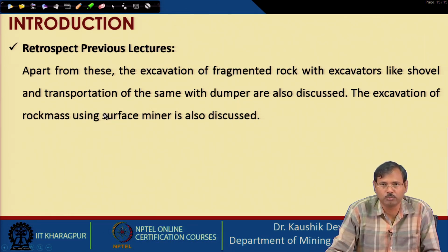That is the problem with the stripping shovel, and it has to work from the bottom of the benches towards the upward direction. But the stripping shovel can dump the material at a precise location, not like the dragline, which dumps the material over an area. However, the cost of the dragline is lesser than the stripping shovel.